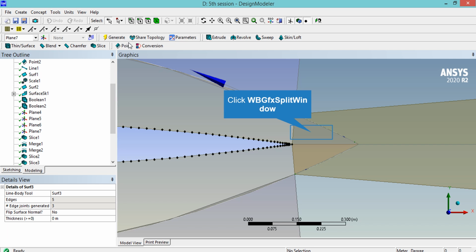As you've probably guessed, now that we have created this surface, it is placed over the triangular faces that we want to omit and over the surfaces that are placed on the right side of our geometry. Therefore, we need to first hide this surface in order to omit the triangular faces, and next we need to subtract this generated surface from the two surfaces that are placed on the right side of our domain.